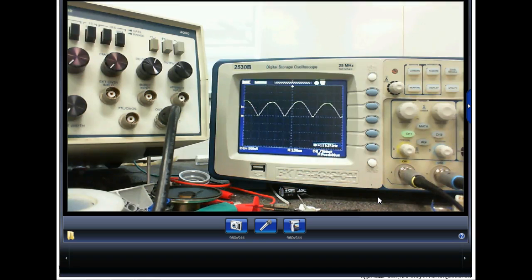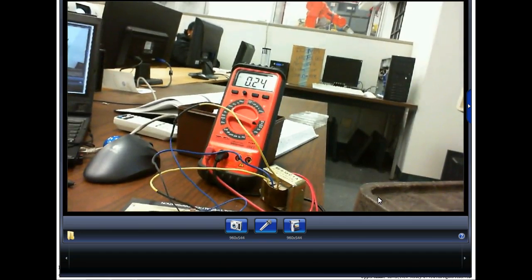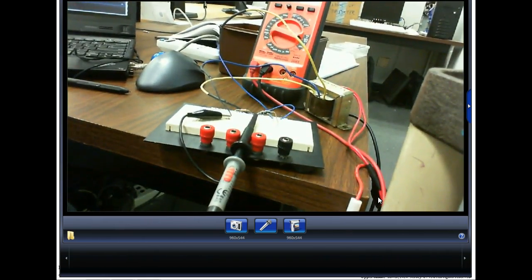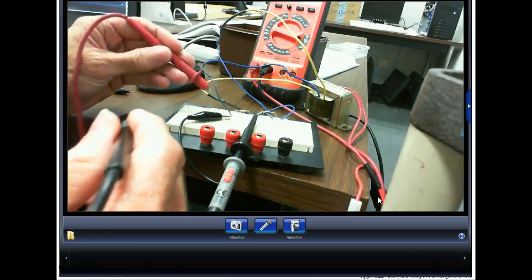And we calculated 5.2 volts. We know it's going to be high because we know the output of our transformer is high now. So we'll turn our meter back on. We just can't measure current with this meter right now. I'm going to measure the voltage across the load. I'm going to put my meter across.